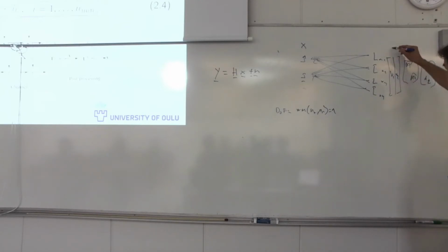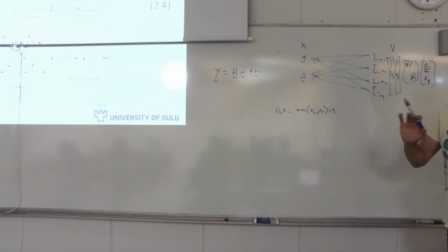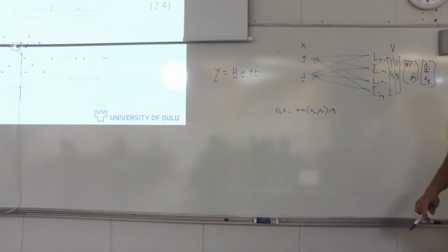B1 and B2. Now this precoding matrix, each of these vectors corresponds to one transmitted symbol. So this precoding vector assigns this symbol to each transmit antenna. Both of these symbols are transmitted from all antennas, or a superposition of these symbols is transmitted from all antennas, properly weighted with the V vectors, so the V matrix.